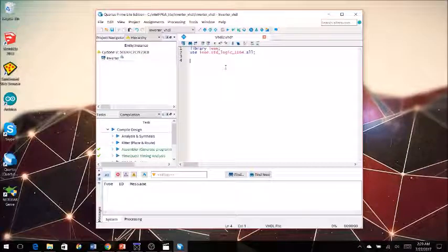The next part we're going to want to add to this program is the entity block. Essentially, the entity declaration defines the name of the entity as well as includes a port list. And the port list are the inputs and outputs that we want that entity to have. So here I'm going to call my entity inverter.